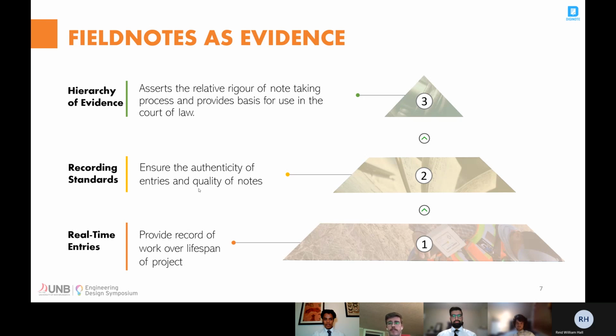In the event of a boundary dispute, with no other evidence, original field notes can be consulted. And this still rings true even if there are natural boundaries or original monuments; the evidence from field notes might still be considered. For field notes to be admissible in a court of law, they must be authentic and recorded during the time of survey. Any erase marks or mislabeled dates could render the field notes inadmissible. It is our duty to ensure that digital field notes can fall in line with paper field notes and maintain the same integrity.